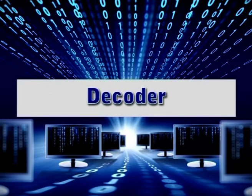Now, let us discuss another combinational circuit called decoder. Discrete quantities of information are represented in digital systems with binary codes. A binary code of n bits is capable of representing up to 2 power n distinct elements of the coded information. A decoder is a combinational circuit that converts binary information from n input lines to a maximum of 2 power n unique output lines. If the n-bit decoded information has unused or don't care combinations, the decoder output will have fewer than 2 power n outputs.